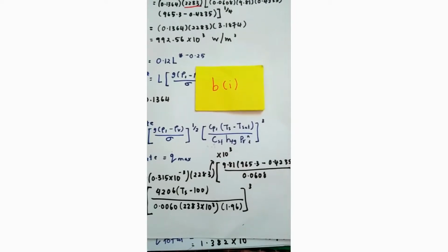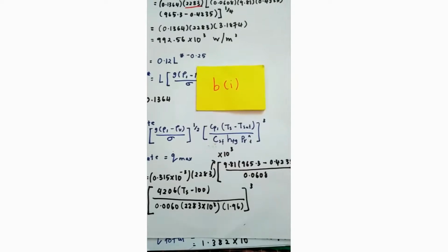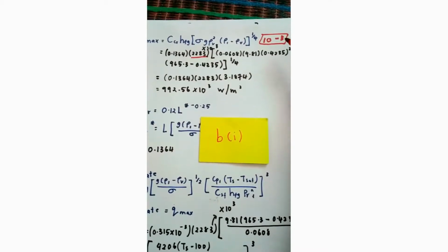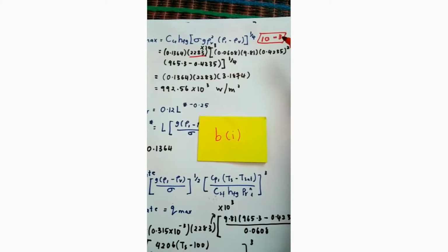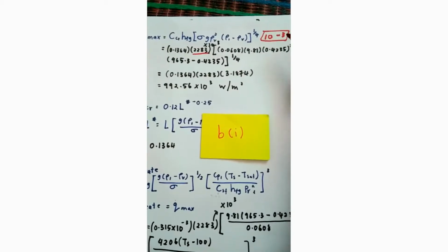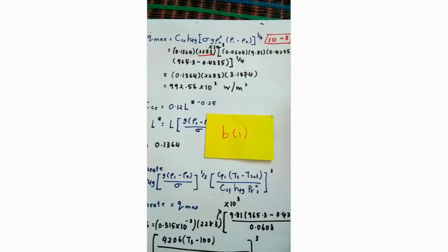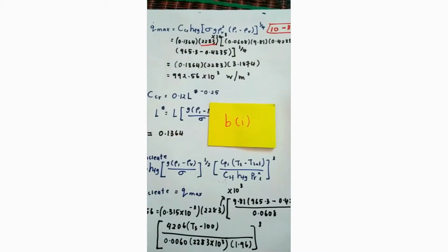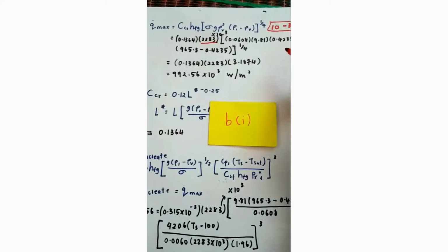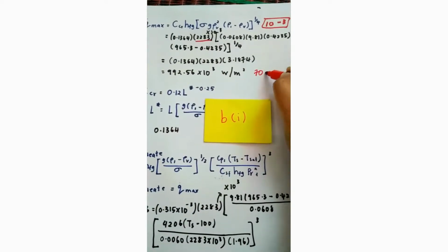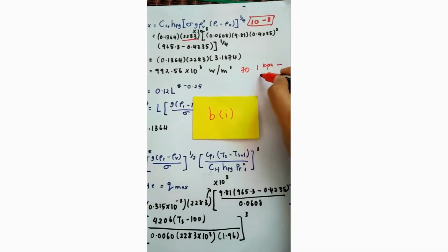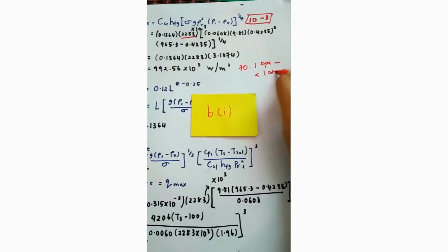In order to get the Qmax, we have to use equation 10.3, which is actually the same as the equation that we used in question A1. But in this situation, we have to choose the properties correctly, which is in between 71 kPa until less than 1 atm.